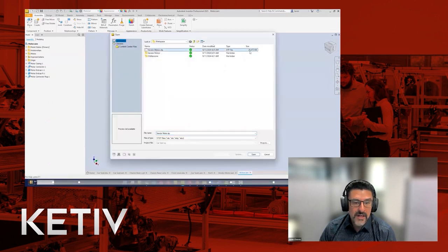If we focus in on the size, initially, right, if we go through the process of importing this over again from the vendor, you'll see this thing is like 20-something megs, right, in size. We don't know if it's going to explode into an assembly or if it's a single part. For us, it's one single part in our system. We want to treat it as such. We don't need the complexity of an assembly. So you'll see some things there, right? The goal is to get this as one purchase part, make it as lightweight as possible, and still know how we connect to it, where shafts go in, where wiring goes in, and how much space it takes up. That's what we need it for.